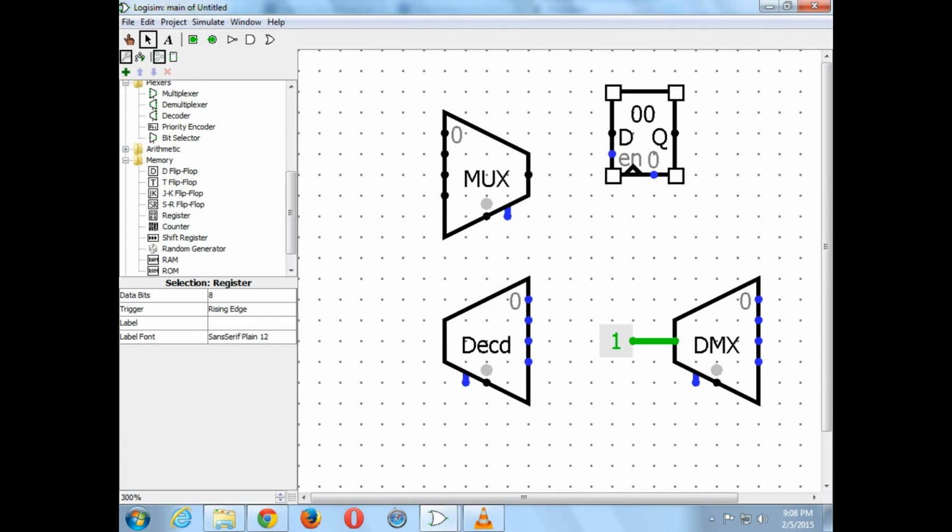And Q port stands for what? That's the output. Okay. Which is why it's called Q. The way it's called Q has to do with a flip-flop, like a D flip-flop, because a register is basically a multi-bit D flip-flop, which operates basically the same way, but it's a 1-bit register, and this is an 8-bit register. I don't know exactly why they label it Q, but generally speaking, that's the output of a register. Well, any questions about what a register is and how to make use of a register?